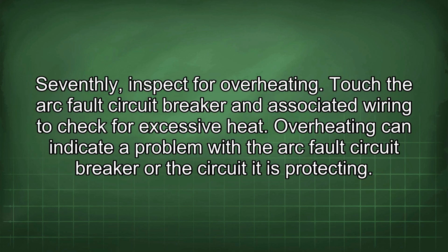Seventhly, inspect for overheating. Touch the arc fault circuit breaker and associated wiring to check for excessive heat. Overheating can indicate a problem with the arc fault circuit breaker or the circuit it is protecting.